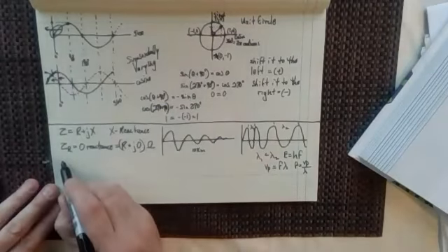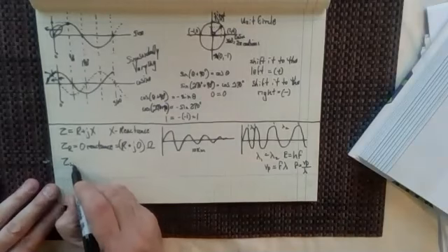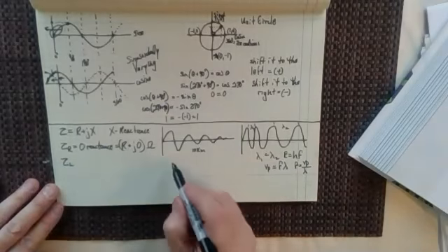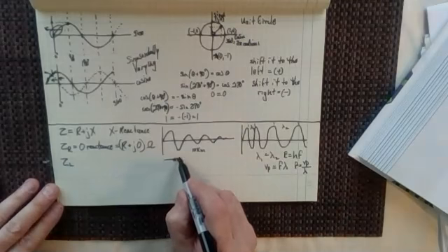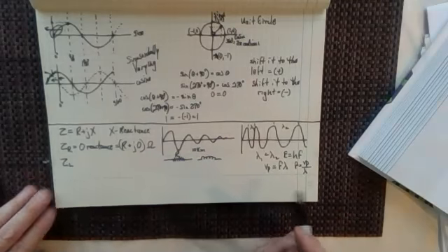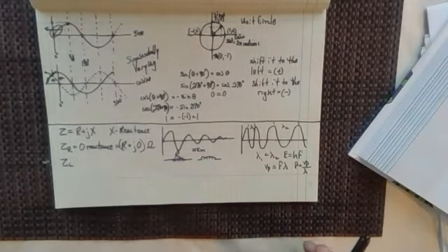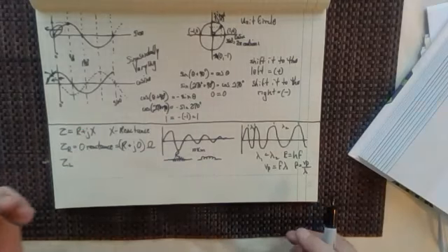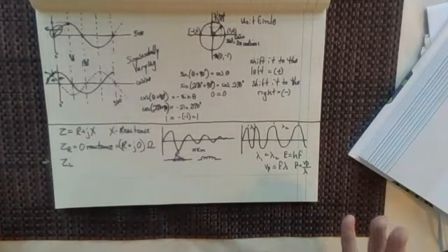That's right. Now, let's draw the three different schematic symbols. Of course, this is my resistor, and then my inductor looks like a loop. The reason it looks like a loop is because that's how an inductor is made. Usually you'll have either a hollow core, which would be an air core inductor, or a steel core inductor.